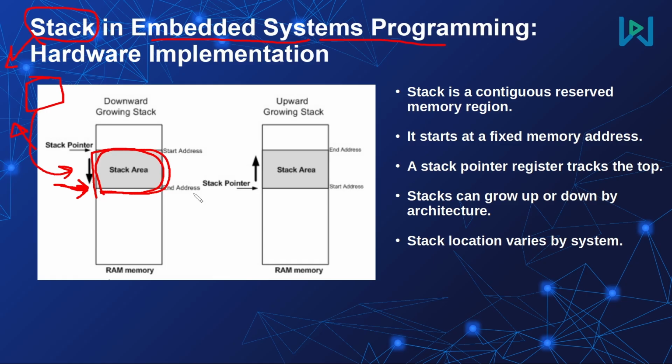The allocation can be done at compile time by specifying the base address and the end address of the memory region to be allocated to our stack. Or we can update the stack pointer to point to a different memory region at runtime.